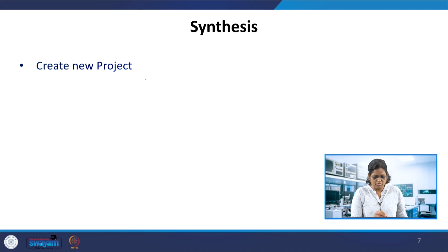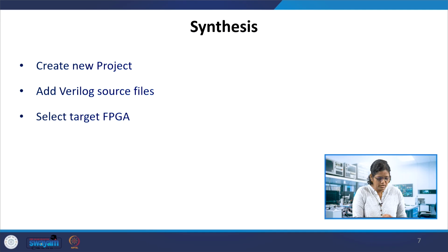Also, what are the points to remember when we create a project in the synthesizer tool? That is, create a new project. When you create a new project, you add the Verilog source files, that is the design file, and the test bench for simulation. Also it needs you to select the target FPGA, that is, which FPGA we will be using.